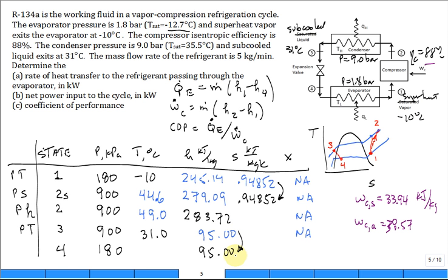And when you do that, you will find that it is two-phase. It's at negative 12.7 degrees C. I should color code that a little different. Negative 12.7 degrees C. And the quality is 0.2886. So almost 30% by mass is now in the vapor state.